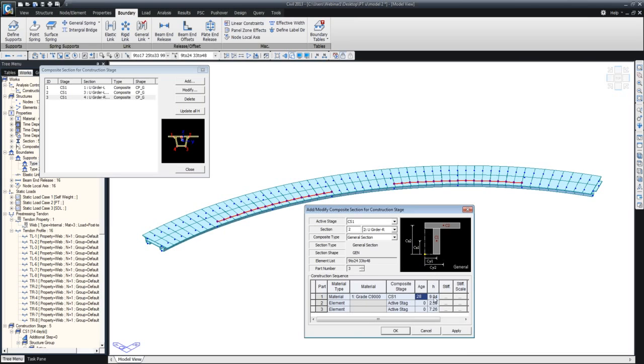By the way, for those who don't know what the notional size is, you may know it by another name: it's called volume to surface area ratio, or something similar to that. It is a different formula, and this terminology is taken from the CEB-FIP code. If you need more details, feel free to ask me in the question box, and we'll talk about that in more detail at a later point.